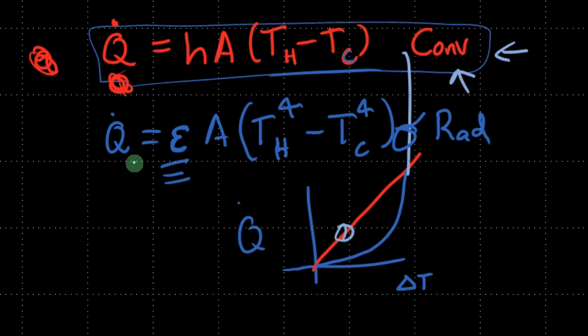The next way to lose heat is through radiation. Radiation is basically losing heat through light loss, sort of. A hot object in a cold room loses heat to its surroundings by emitting light. You can read the details about it later. But it has a relationship related to the hot and cold temperature to the 4th power. Therefore, it sort of picks up speed at a higher temperature. We can expect the heat loss due to radiation to be much more than the heat loss due to convection at a very high temperature.